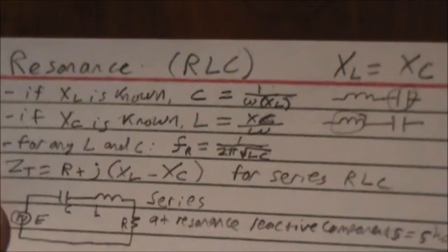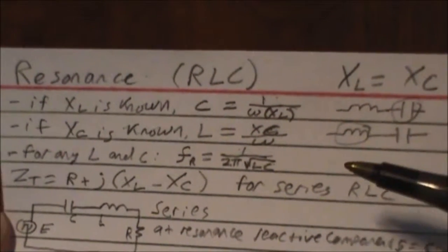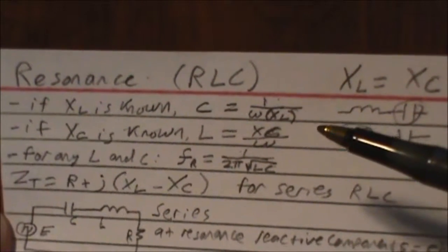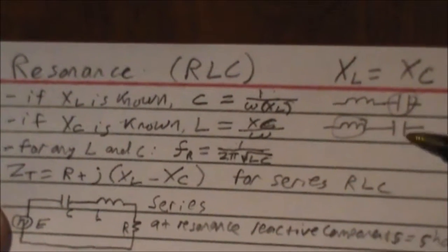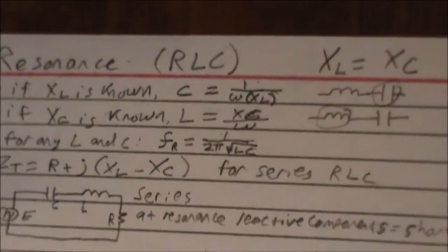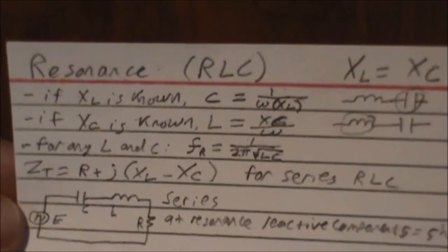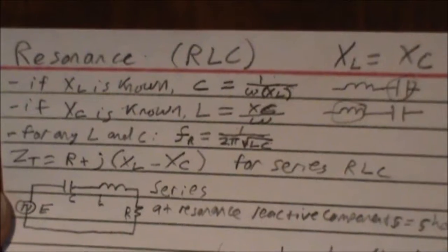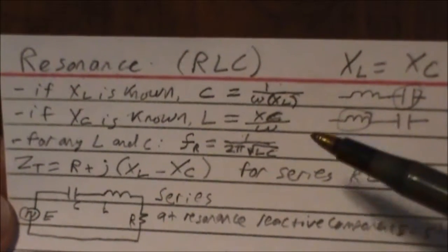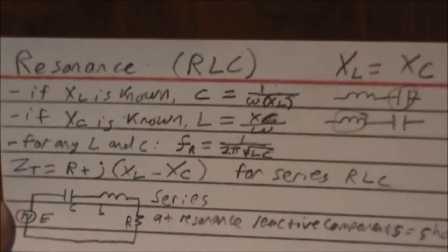Such as in a Tesla coil, you would want to match up your capacitor with your transformer. Sites like the Geek Group have published tables and whatnot for transformer to capacitor matching. And from there, you can use this simple formula to find out how much inductance you want on your primary